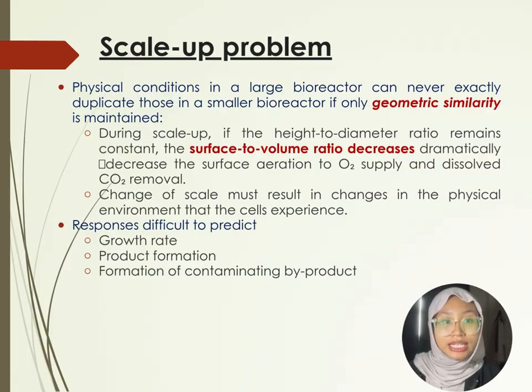As the reactor size increases, the surface to volume ratio decreases significantly. This creates challenges because less oxygen can enter the culture medium through surface aeration, while the removal of dissolved carbon dioxide becomes less efficient. As a result, the microorganisms experience a different physical environment compared to the small-scale reactor. These changes can affect cell behavior and make the process performance difficult to predict.